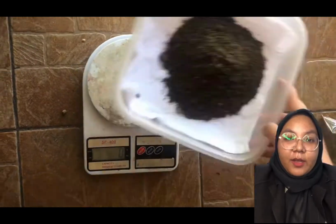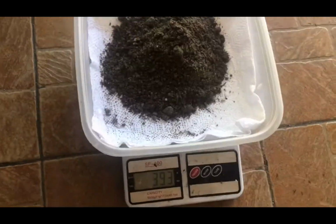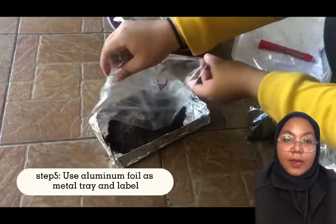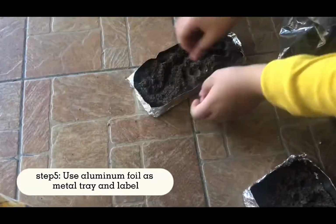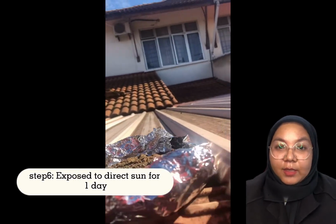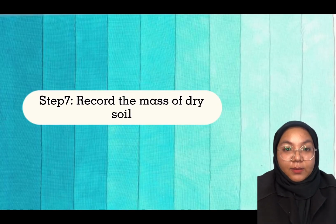And record the mass of the soil and tray. Use the aluminium foil as the metal tray and label it. Next, we need to expose the soil into the direct sun for at least 1 day. The next day, take the sample and record the mass of the dry soil.